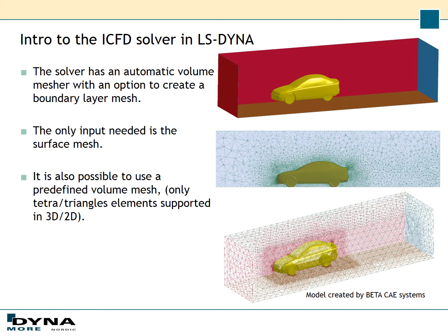The ICFD solver has an automatic volume mesher with an option to create boundary layers. So as a user, you only have to create the surface mesh, and then the solver will generate the volume mesh. But it's also possible to create your own fluid volume mesh if you want that.